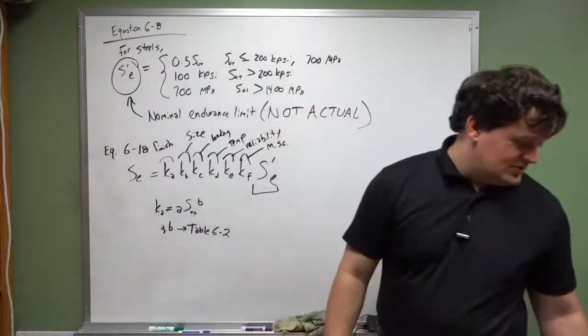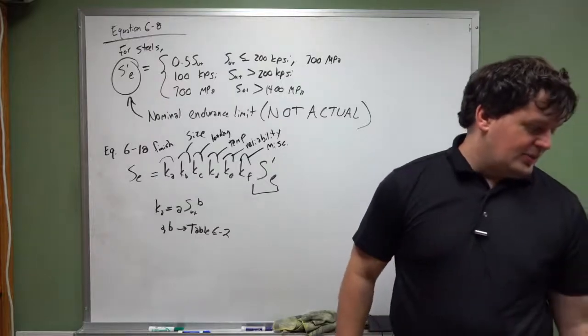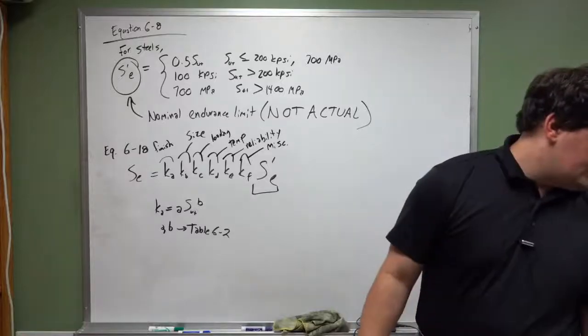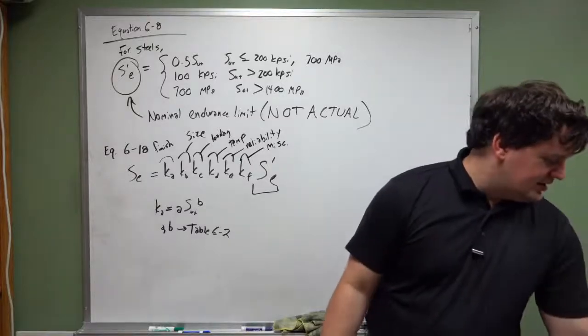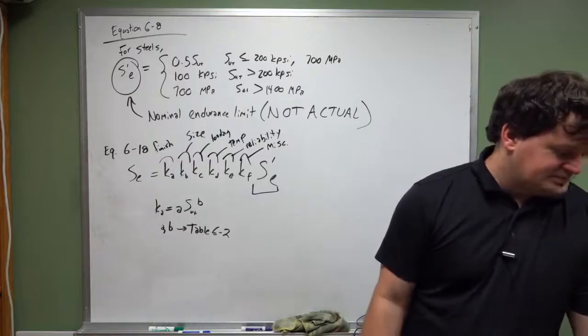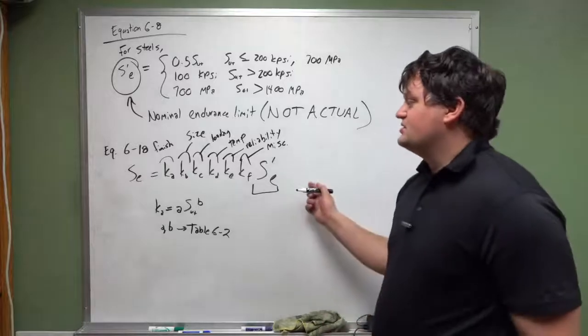such as case hardening, parts that come in with some corrosion, parts that have been electrolytically plated, etc., etc. So these are all factors that affect this endurance limit.